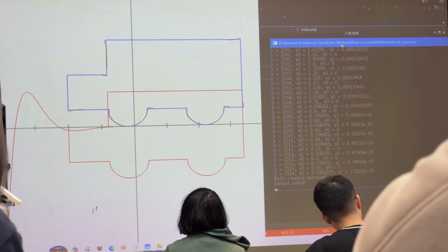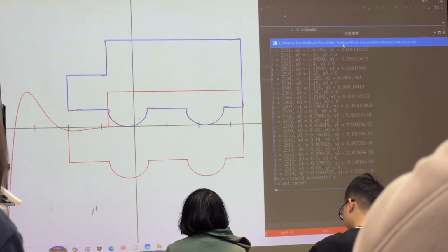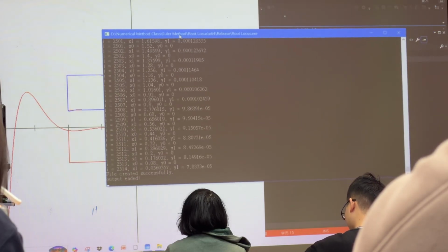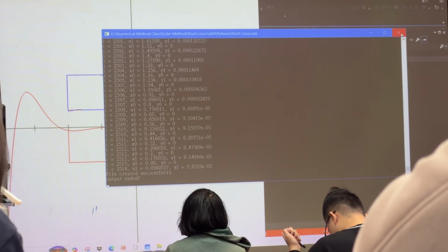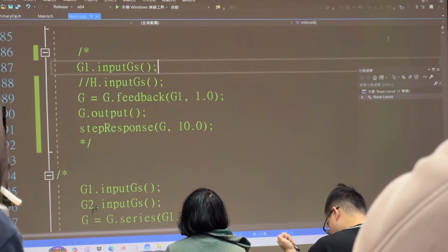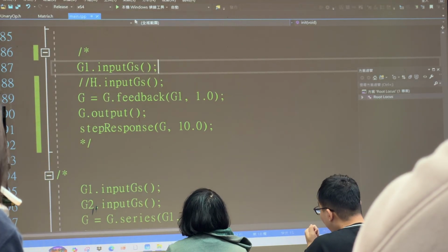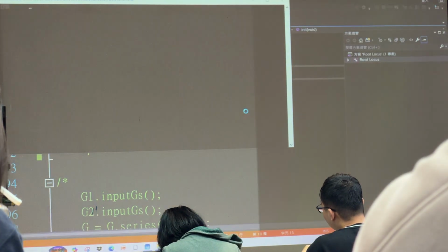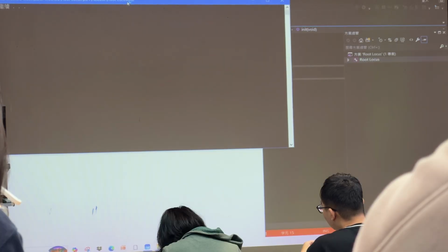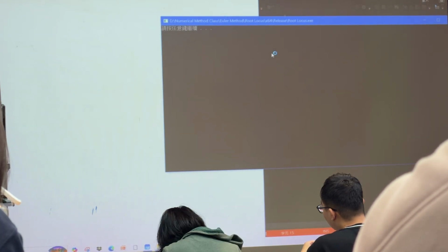So now if I increase velocity, the dynamic error will be even bigger. So let's do it again, but this time I will set a higher velocity value rather than 200 millimeter per minute. Now I will set it to like 1,000, 5 times higher. And you will see the tool path gets a little more distorted. I will show you.